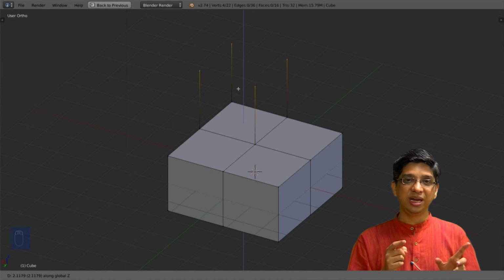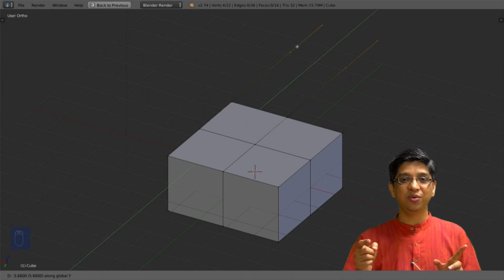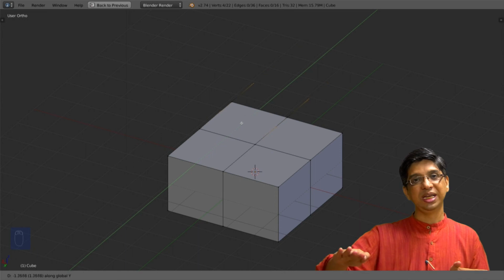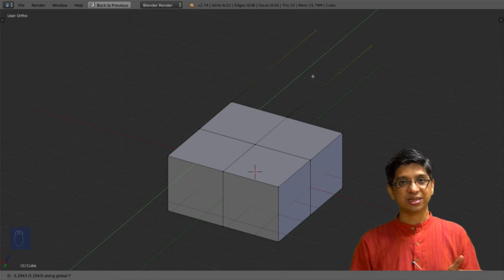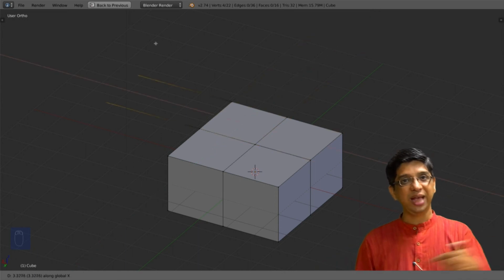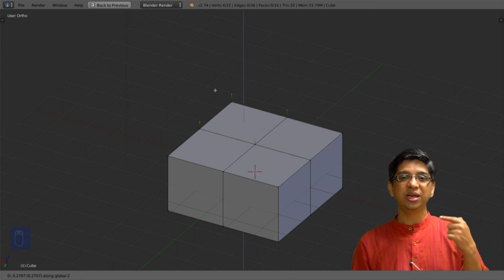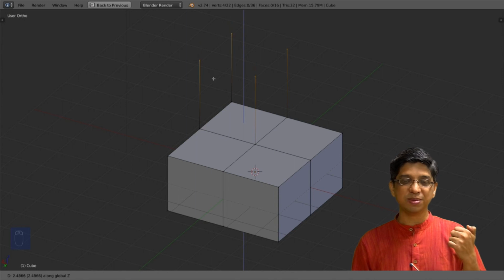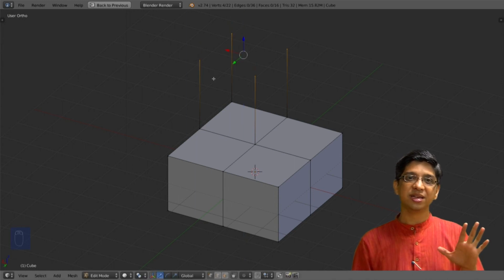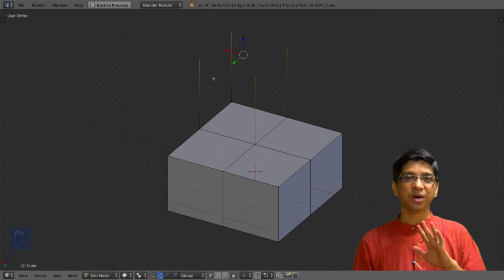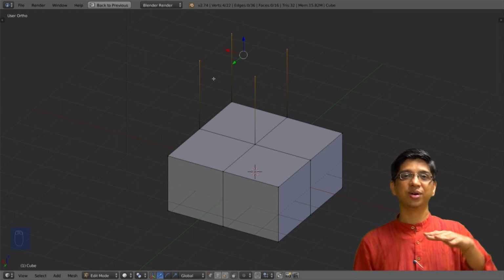If I press Y, it will go in horizontal direction, and now you can see that they are going horizontally. Or if you press X, then it will go in X direction, right. So this is how you can actually press, maybe Nitin has pressed Z again and he has left clicked on that to confirm that this is the height I want these 4 vertices to be. So we can edit vertices, edges as well as the faces to extrude and get to the desired shape.